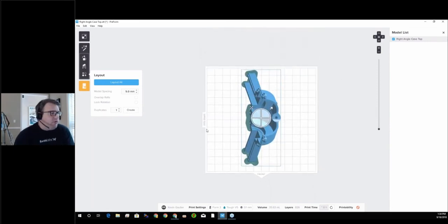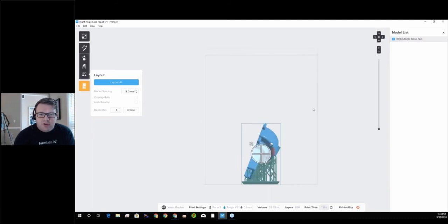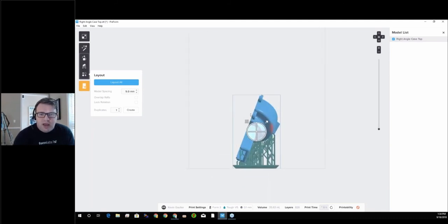So the Form 2 is going to do a slide and peel, and that slide goes in this direction, the direction of the wiper. So if we were to leave the part as is, the part would actually be getting some torsion on it, trying to peel the part off these support structures in the left to right orientation. So all that force is divided across this much width.